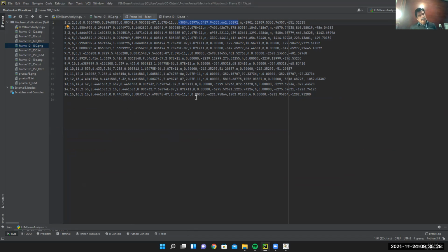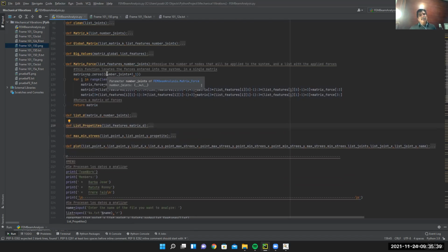Remember, when you have a structure, you have external forces from the wind, from the weight, and from the pressure. The problem is that on the supports, those points cannot move, cannot rotate. And then you have a reaction from the foundation. That reaction is the external forces which do not allow this point to move. So you have to calculate them after you solve for the displacements. These are not data.